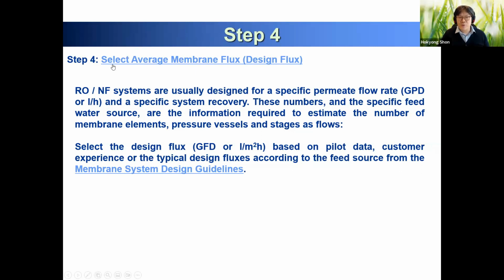So in step 4, we focus on average membrane flux so that you can estimate the element number, pressure vessel number, and stage number. That's the reason we need to make sure of the average membrane flux.